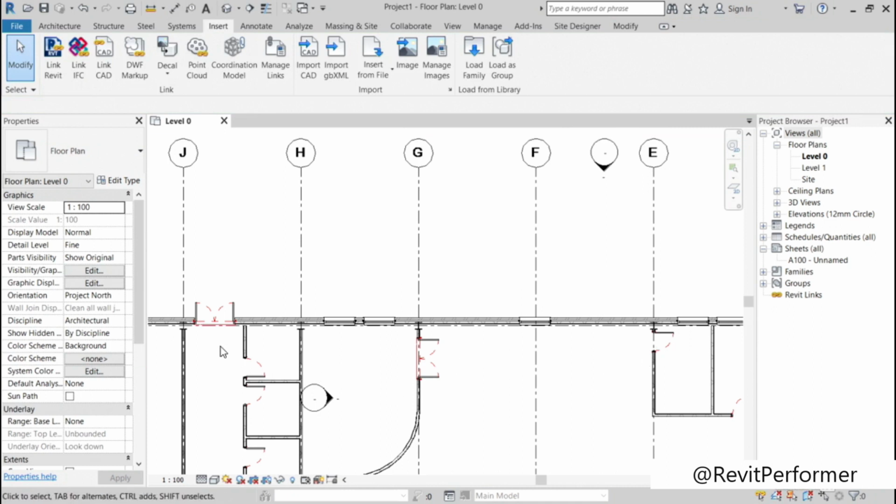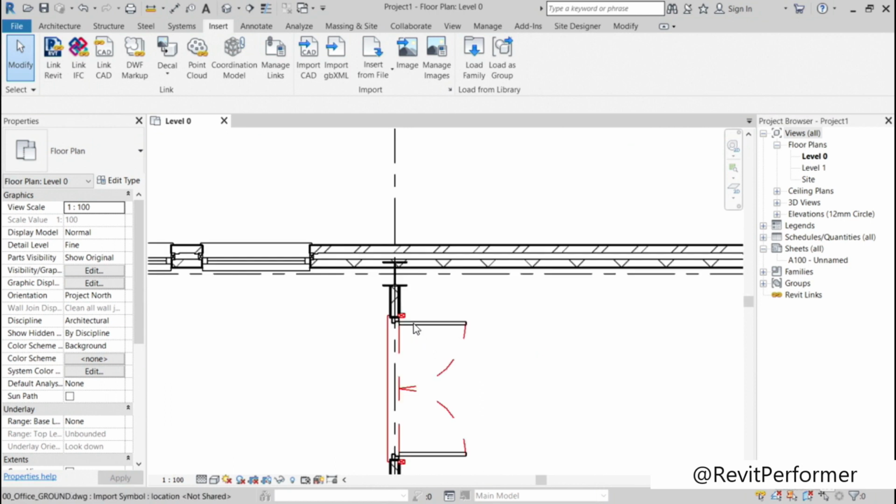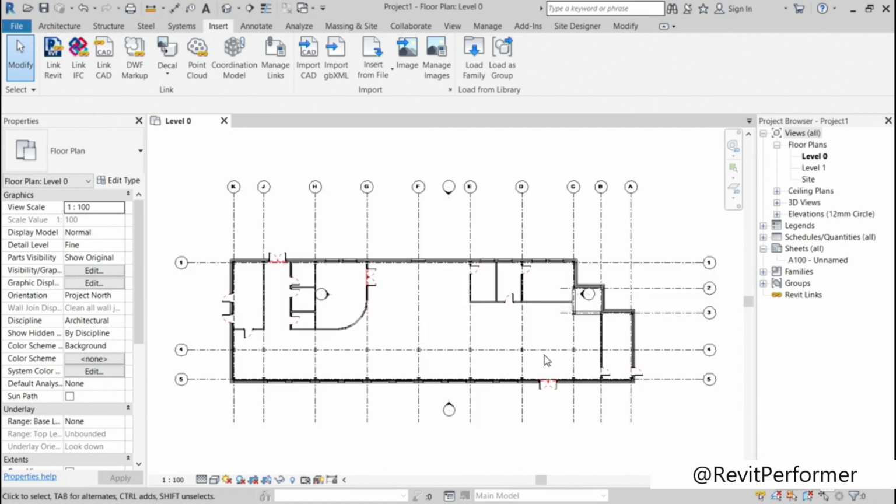And it does depend on what layer, what part of the door it's using. Can you see that? The actual door itself, the physical door, is obviously on a different layer. But all the other extraneous parts of the door are using that layer that I selected and put the override in on. So if I just double click on the wheel to zoom extents, you can see all the doors have that dashed red feature going on like so.